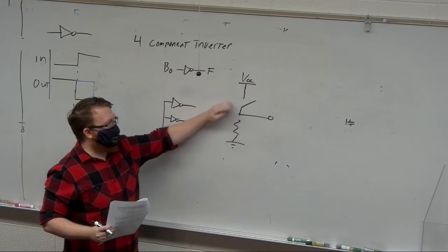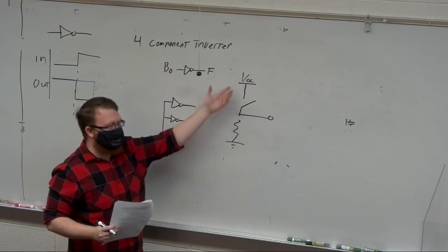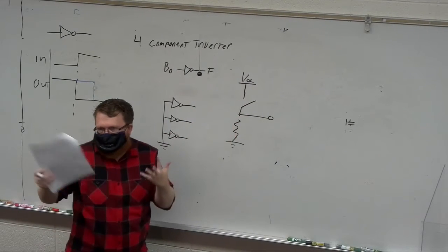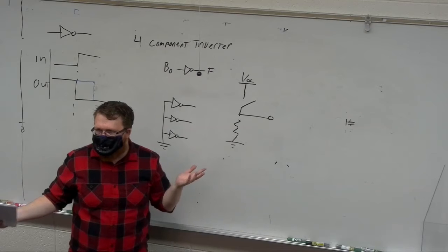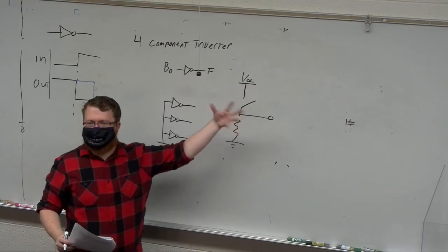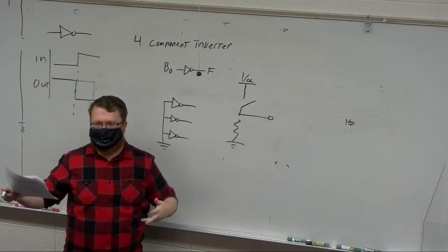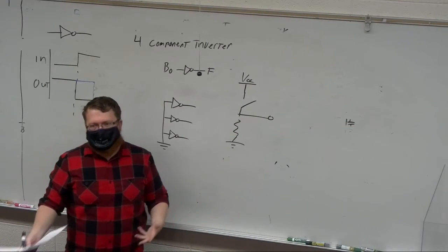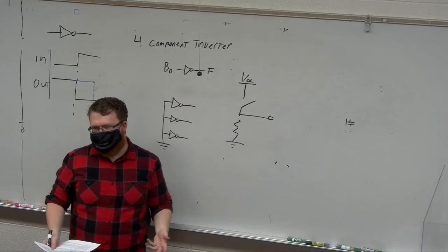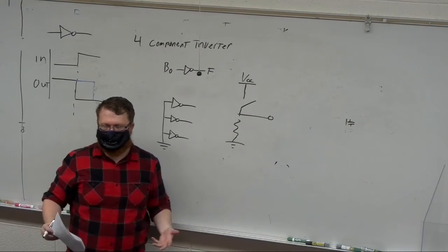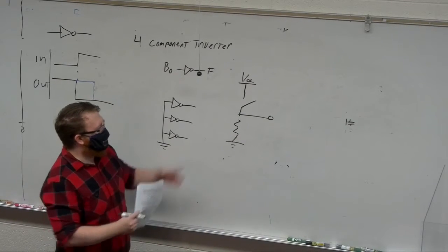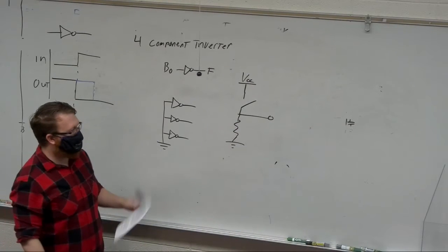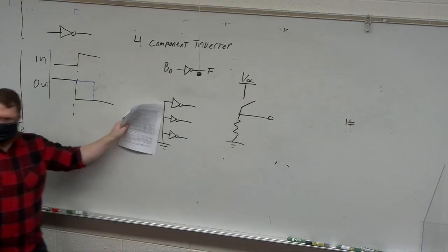In this case, we're broken. If the switch is closed, it is VCC. If the switch is open, it's something, and that can change. And so that can start randomly switching up and down on the output and creating unnecessary power consumption. And it could also introduce what we call switching noise, which can affect any other signals going on. So it's not desirable to leave random floating inputs. So we want to explicitly tie them down.